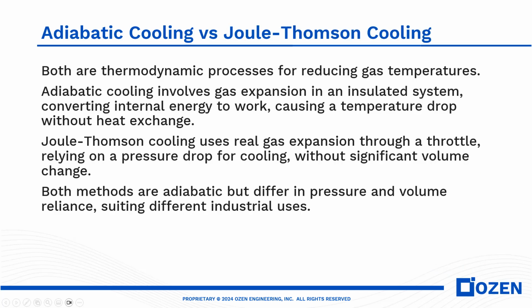A little bit about the difference between adiabatic cooling and the Joule-Thomson effect. Although they are similar thermodynamic processes that reduce the gas temperature, they do this in different ways. In adiabatic cooling, as I said, we mostly rely on the expansion of the gas in a closed system without any heat exchange with the environment.